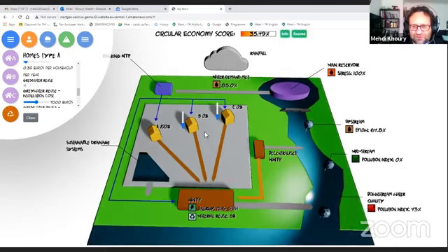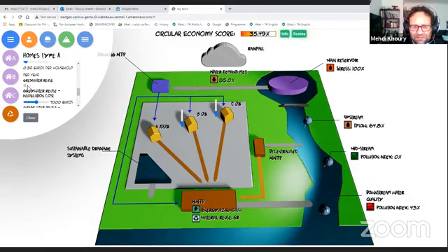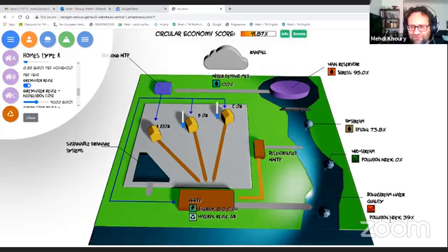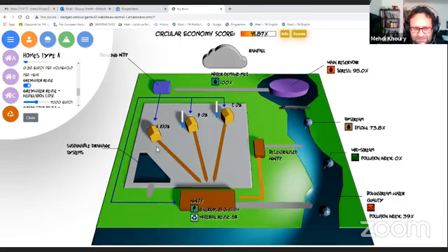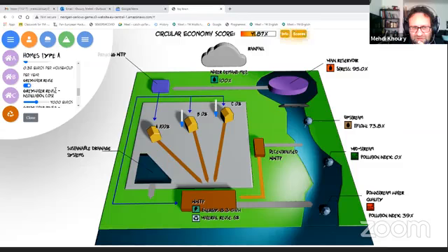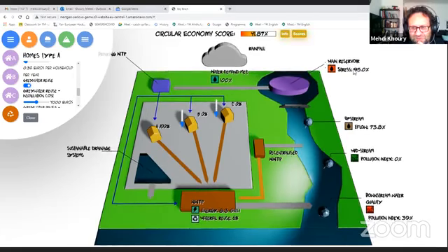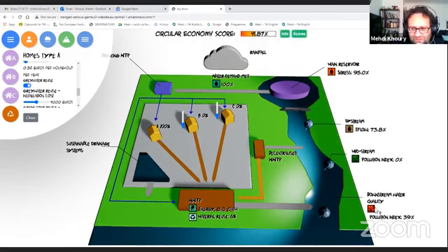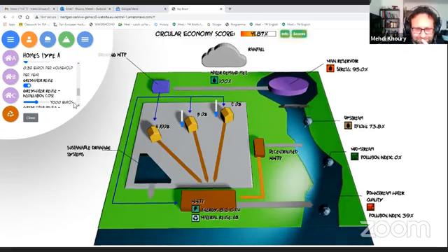Now, what about gray water reuse, another alternative technology? So if I put in gray water reuse, I'm going to click on it. And then we notice that it's much better at saving water. We save more water, but as far as we can see, the pollution, instead of being reduced to 13 or 14%, is still around 39%. So gray water reuse seems to be quite good at reducing water stress, but it's not as good at reducing the COD concentration and the pollution problems.